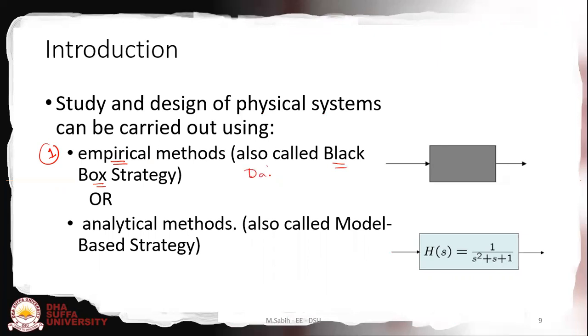the data. यानी आप कुछ input apply करेंगे और output को observe करेंगे. So we apply a signal, for example a step. System might be at 0, आपने उसका step apply किया 10 units का, and you start observing the output with respect to the time, और output जो है इसकी किस तरह से vary कर रही है.